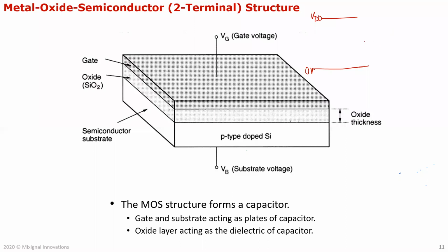And if you want a 1 output, you want to connect this. So let's say this is the output terminal, right? If you want to convey a 1, you want to connect this to VDD. If you want to convey 0, you want to put this to ground. You want to short this to ground. That's basically what it is. That's your digital circuit.